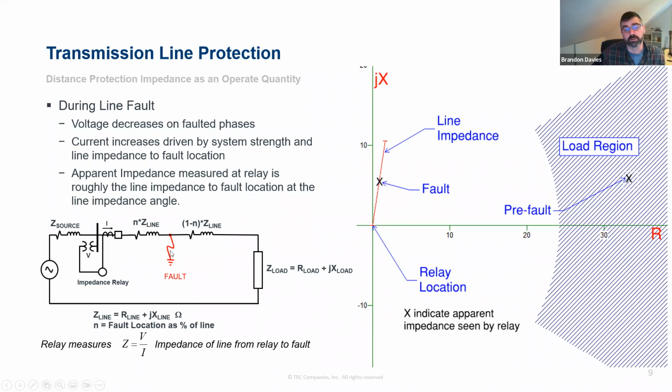But it's still a concern, and you can still have arc impedance. But a lot of the faults are going to be things like a line-to-line fault, which could be two conductors swinging in some intermittent wind and touching. That could be your fault. Or a lightning strike could have a short arc across an insulator or something like that. That would be your fault.